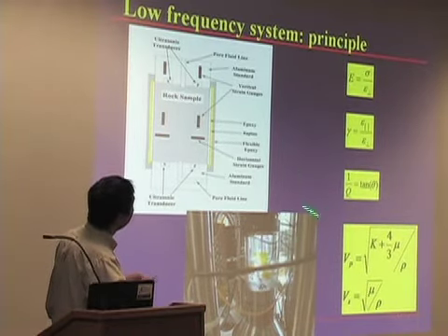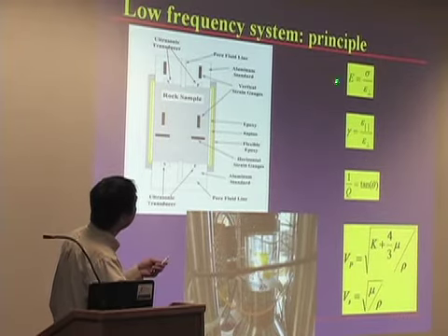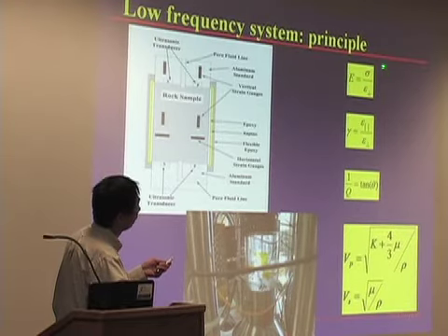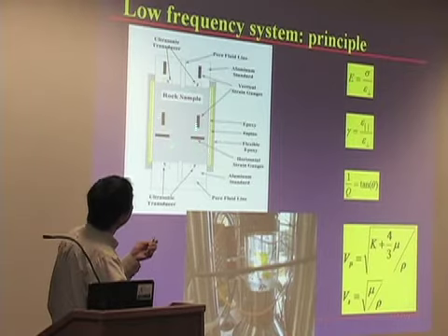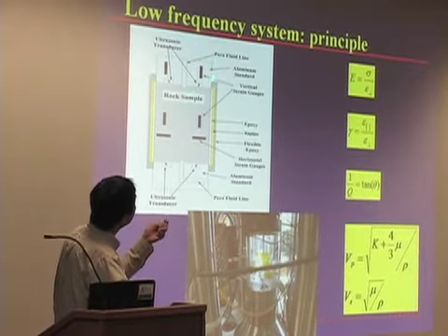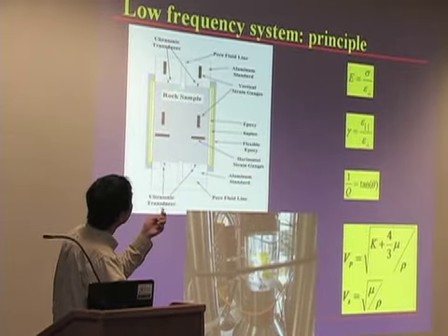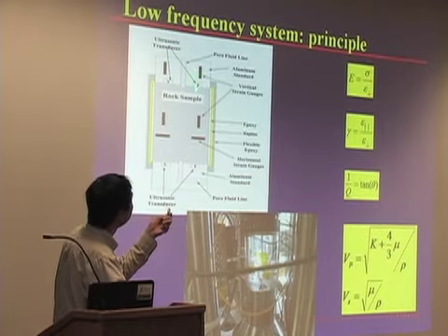And this is the theoretical principle, but for practical reasons, we actually do not really measure the stress, because stress is much more difficult to measure compared with strain. What we do is, along with the sample, we put another piece of material with well-known properties, and we also measure the strain output from that. We call it the standard material.